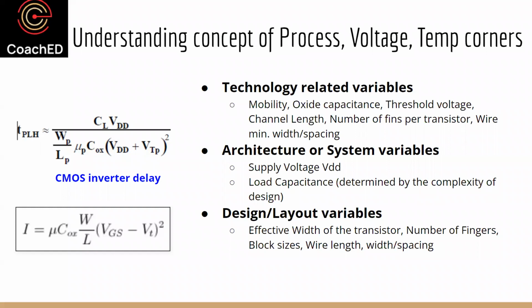Same thing on a chip could happen, where the supply could actually be drooping because there could be a lot of activity happening suddenly, and therefore some sort of inductive effect could happen. There could be some resistive drops happening, which means voltage could be lesser. And then additionally, there could be other things. For example, on my motherboard, where I have a voltage regulator, that could be misbehaving and things of that sort,